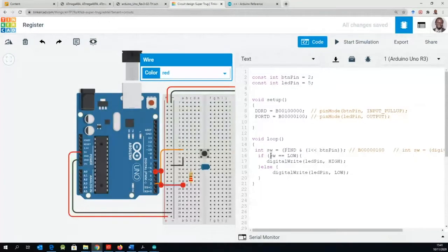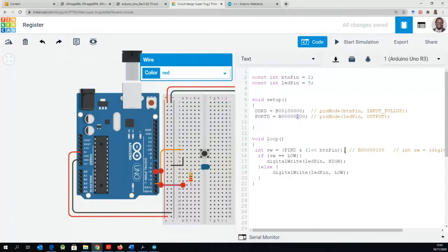And then what we also want to say is that, okay, now we have sort of binary on there. We want to make sure that the very first bit is written into the switch, so we don't mistakenly write 0 or anything. So this part, the logic here, we achieve this. Basically, we just simply read the switch, or read the pin D, in B, so pin D2, and after reading it, we want to shift it all the way back down.